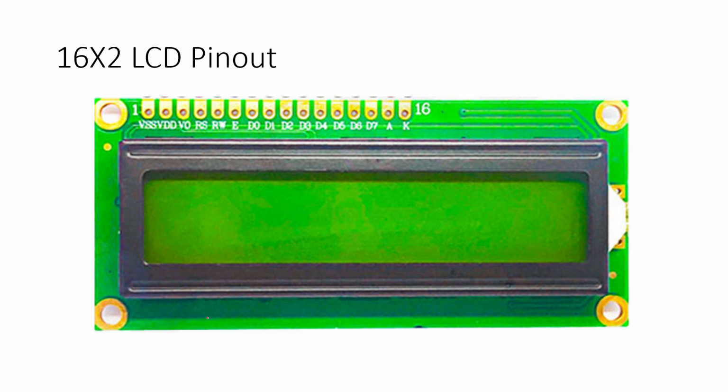This type of 16x2 LCD you might have seen in many places, like in your major projects, minor projects or hobby projects. Every 16x2 LCD will have 16 pins, numbered from 1 to 16. The last two pins, A and K, we'll use to control the brightness of the LCD. That is, we'll be connecting a potentiometer here. You can use a potentiometer, and by adjusting the value of the resistance between A and K, the brightness of